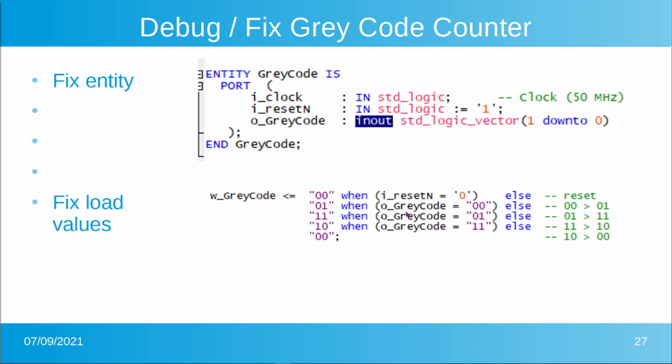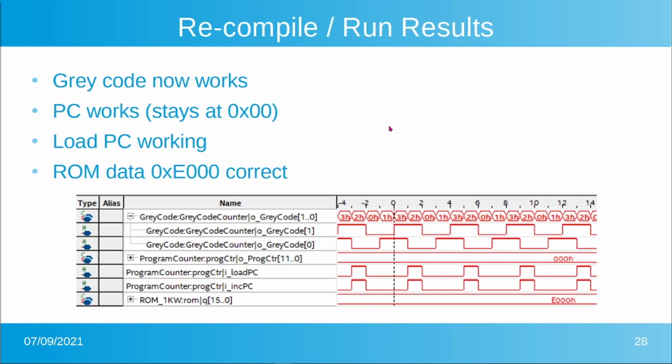Once we use something down inside of here that was an output pin, we have to change it to an in-out to tap it back into the FPGA. So that'll fix the gray code counter. When we run it, we can now see it working. So it's going from state 0 to 1 to 3 to 2 to 0, and it just keeps looping forever, just like it should.